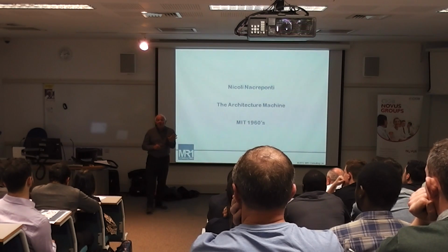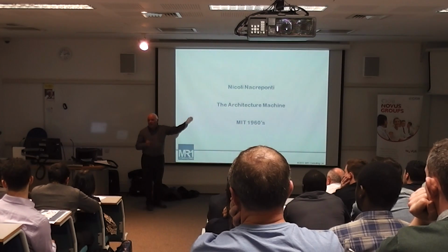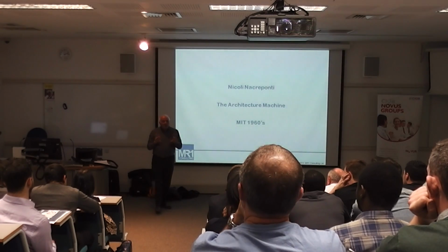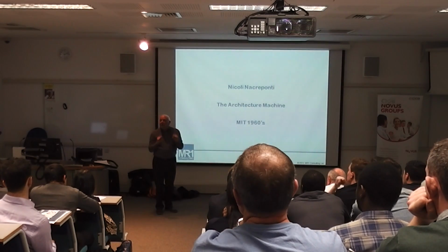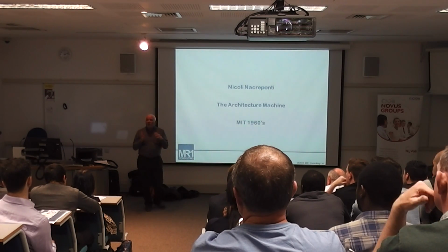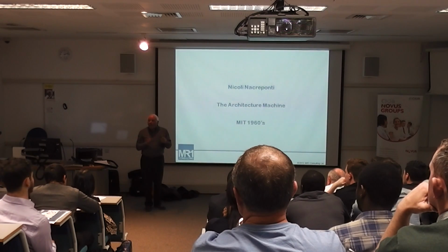Is there a room on the inside? Yes. Is there a room on the outside? No, therefore this is an external wall specification, and it automatically put in the wall that had been specified. If it had a room inside or whatever, it would put in an internal wall based on the specification. And then it would reorganise, recompile all of those spaces so that you ended up with the working space that you required once the construction, the architectural fabric was in place.